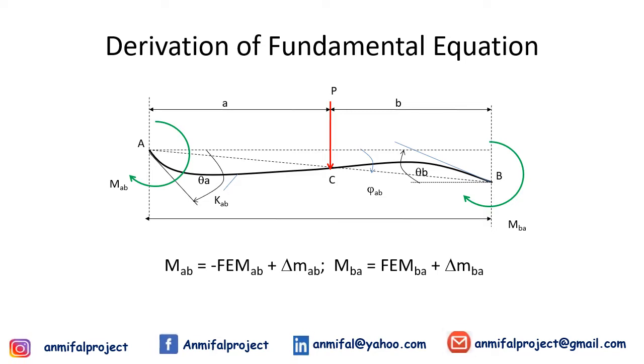So we have a slope at the end of each of the beam, E and B, or next we call them theta E and theta B. That indicates the tangent of the elastic deformations at the edges of the beam, E and B. Then we have moment EB or BE, at each end of the beam.